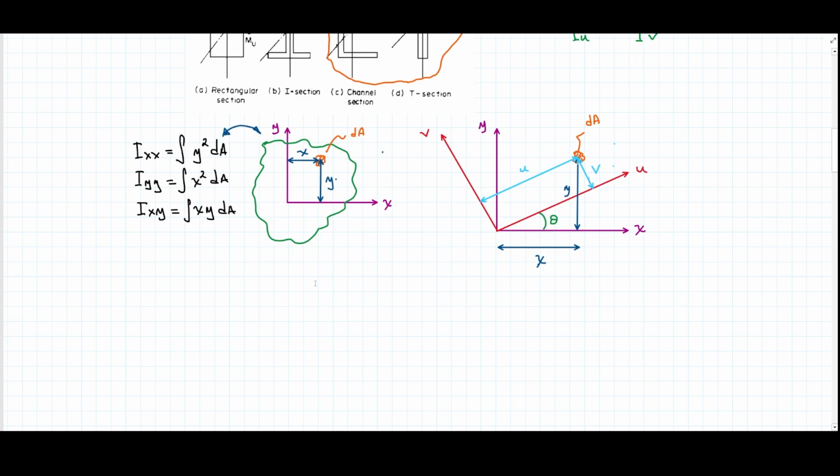Good. So let's then try to calculate, as the principal axes are those axes where the product of second moment of area is 0, it makes sense to start defining that term, this product of inertia, for this case. Because if we can find the value for that product second moment of area, equate it to 0, then maybe we can find an angle that would tell us how it is oriented with respect to the xy Cartesian coordinate system, right?